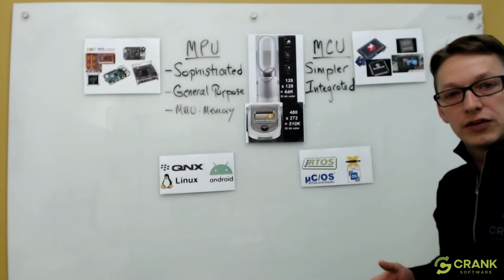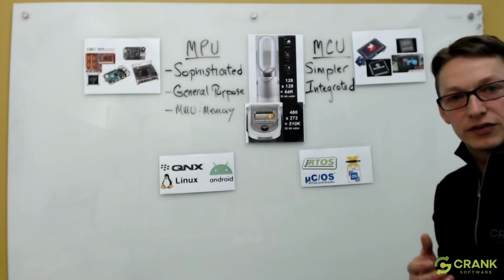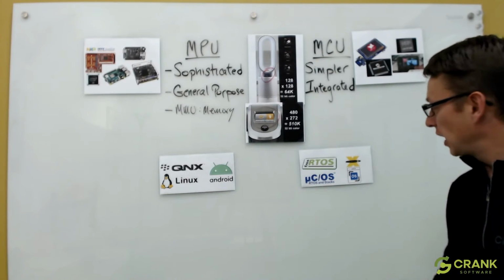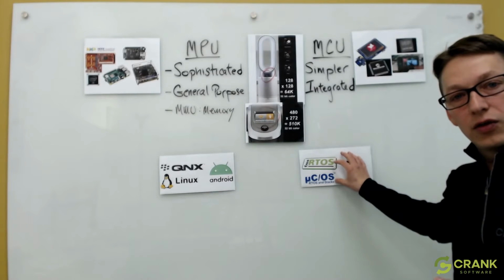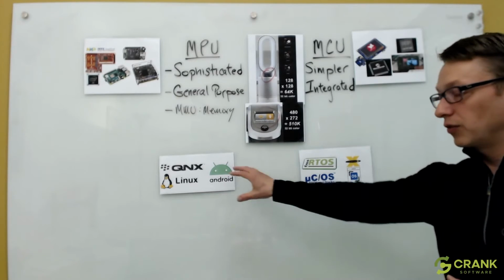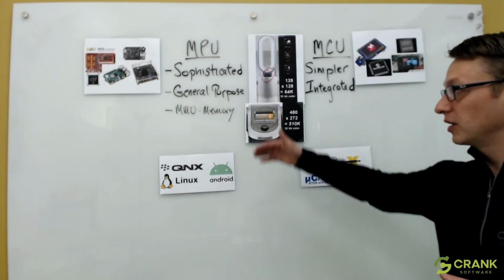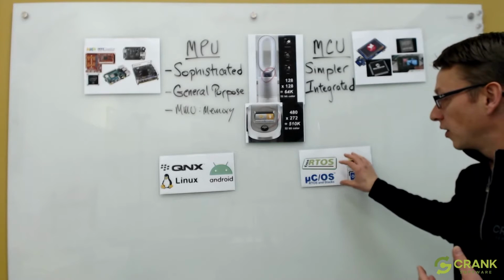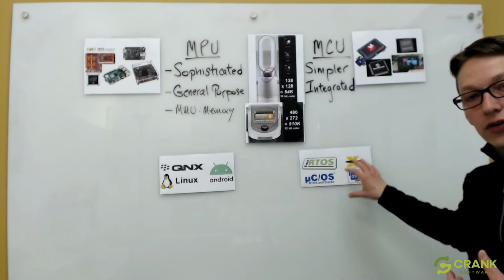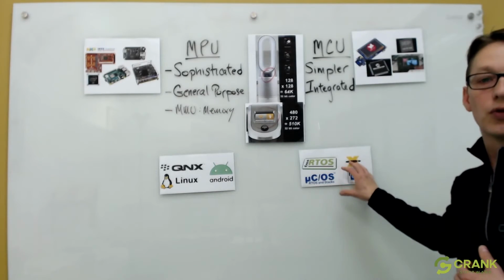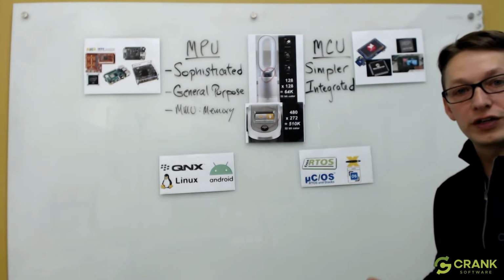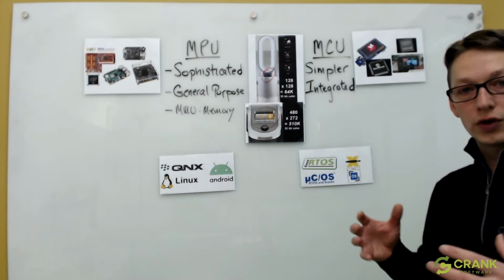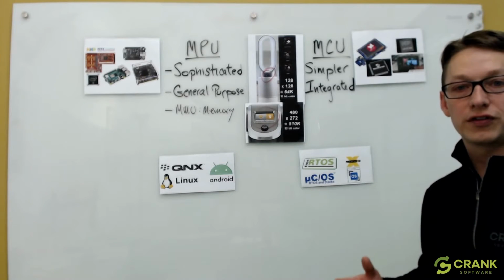A real-time executive offers many of the operating system functionalities in terms of task management, synchronization, and timers, but it offers it in a way where that isolation you get with the process model, which comes partially because of the MMU factor, the memory protection, is not there. It's also a different mindset. Typically when you're working with these systems, you're not looking at soft resets. What you're doing is assembling the entire system to work together in one system image, one system load.